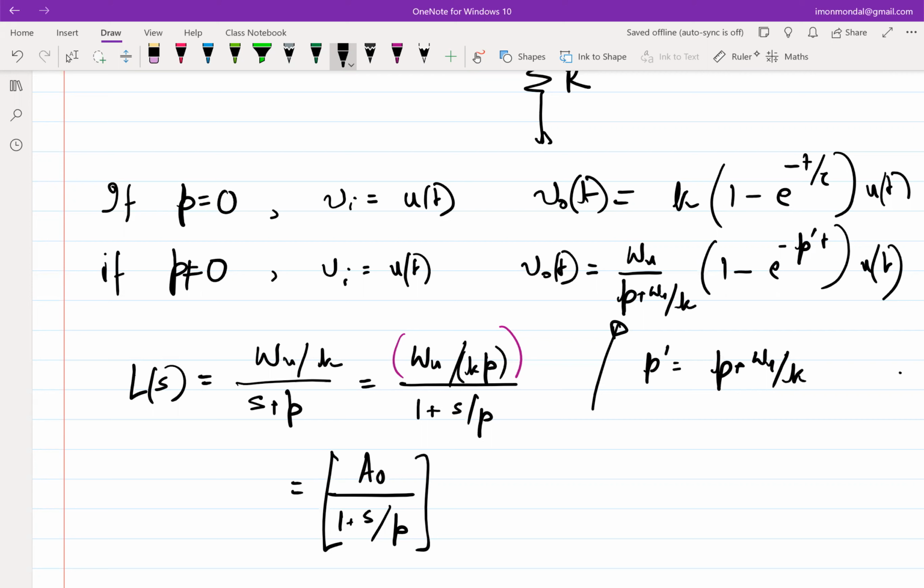It will start from 0, right? Because you note that your transfer function is low pass type. So it's some k times 1 by 1 plus s by omega u loop, which means at DC, your closed loop phase is 0. And it will be minus pi by 4 at omega u by k. And it will settle to minus pi by 2 as omega tends to infinity. Okay, so if that is the case, then you will have some term which is tan inverse omega by omega u loop. Does that make sense?